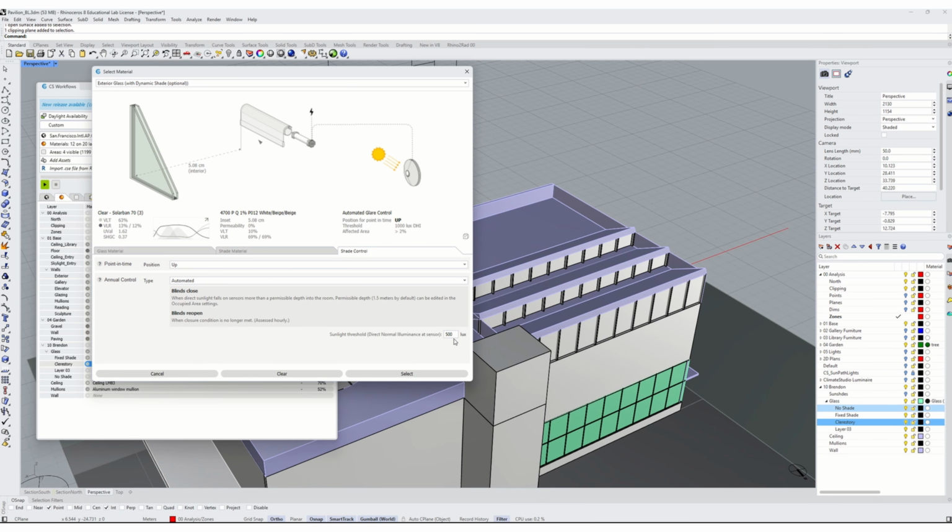In this case, we can set that threshold. I think by default it's at 3800 lux, which is a good default for this, especially because our shades are 10% transmissive. And if we have a criteria of about 300 lux in here, that means that if light levels get to be 3800 lux, it will drop down to 380 lux, which is very close to our target.